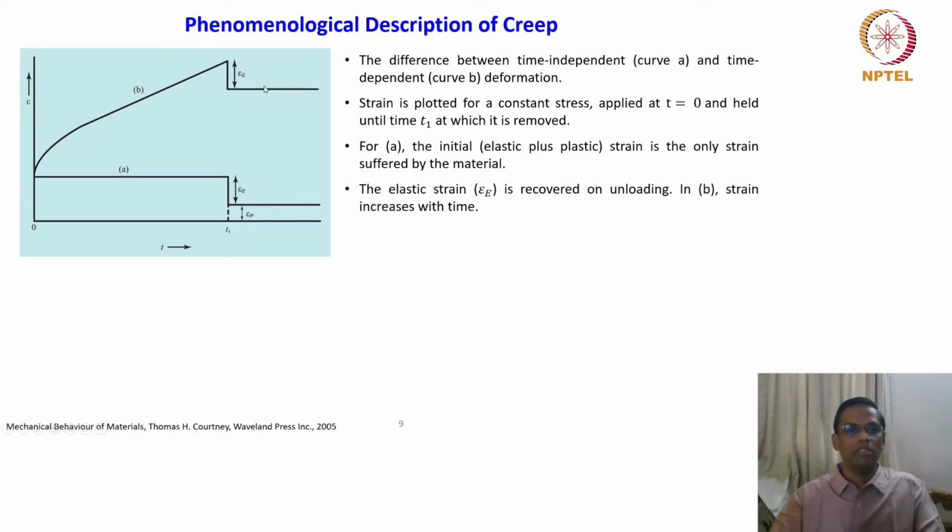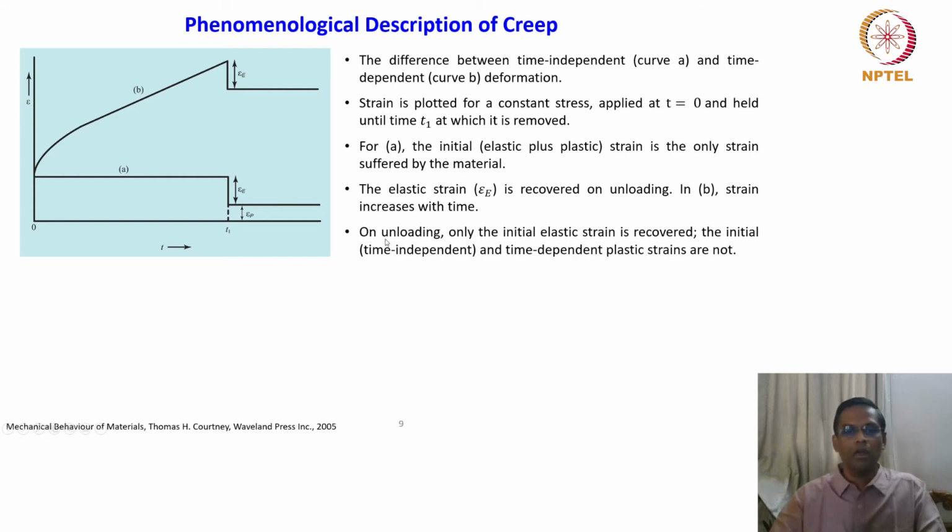Here we are not talking about only the elastic plus plastic strain, as is shown in A. Beyond that, they are all pure plastic strain, right? On unloading, only the initial elastic strain is recovered, and the initial time dependent and time independent plastic strains are not.